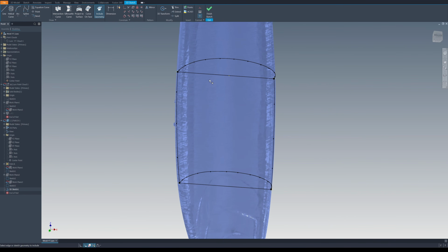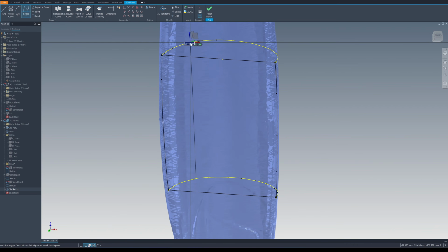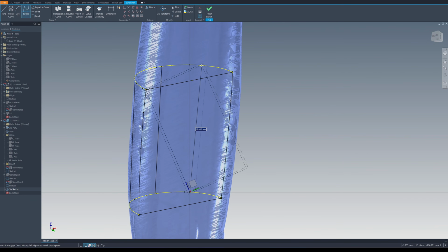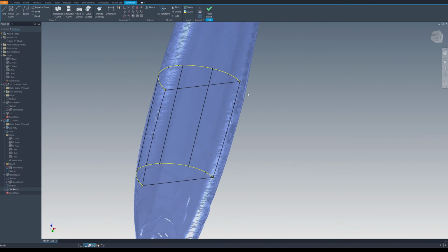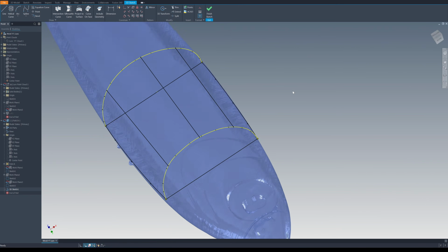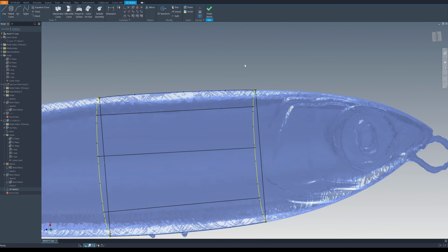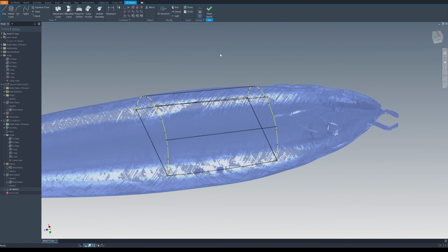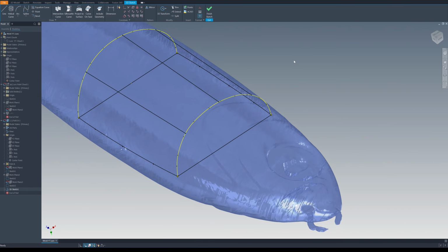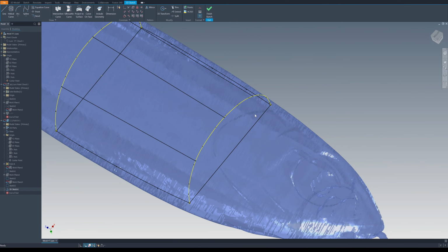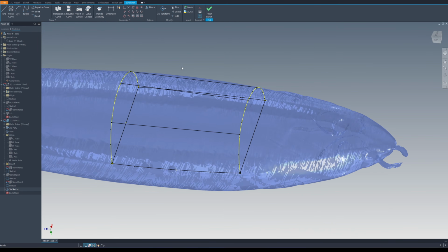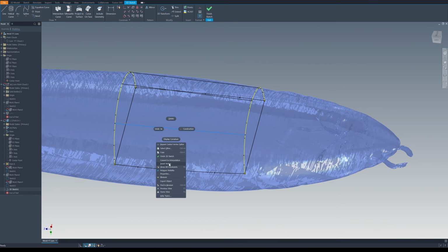Before that, I need to include the geometry first so that I can snap it. Placement of the rail is also important. When you are doing a loft command, you need to place it correctly so it will form the shape of the part, especially the grills one. I'm going to show this later. And insert vertex.